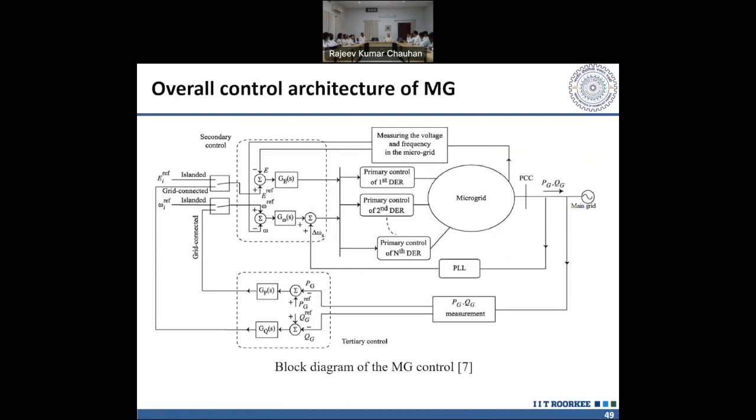बिल्कुल ठीक है. अब from voltage point of view, अभी हमने बोला कि if I will switch on the load, what will happen? The voltage will fall. जब हम जनरेटर को रन करते हैं, जबकि नो लोड पे, you will have a voltage. अब जैसे जैसे लोड बढ़ेगा तो क्या होगा? वोल्टेज कम होगा. This voltage will fall down. Voltage will fall down, speed will also fall down. So in case of the synchronous generator, the speed is falling down, my frequency is also falling down.